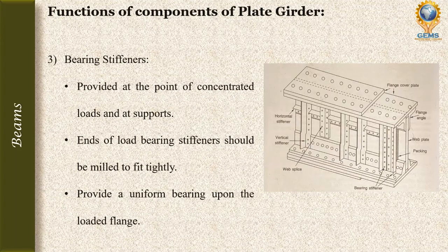Third component is bearing stiffeners. These bearing stiffeners are provided at the point of concentrated load and at supports. So the bearing stiffeners will be provided at two places. One at the point of concentrated load, where the load is acting.